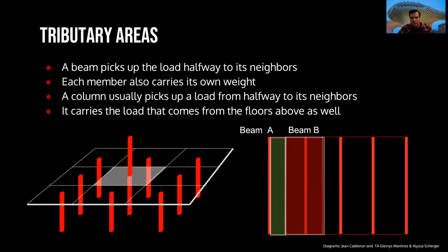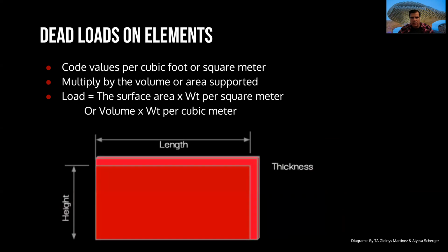And we arrive at the conclusion, for example, that this surface is 5 square feet, and multiplied by the particular thickness, we will have, for example, 6 cubic feet. And what we need to do is just multiply that number by the weight of every cubic foot that we had, and that will give us the weight of the dead load of the elements.